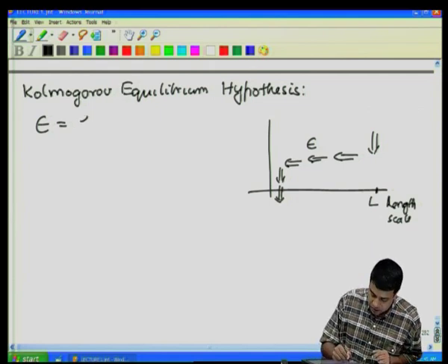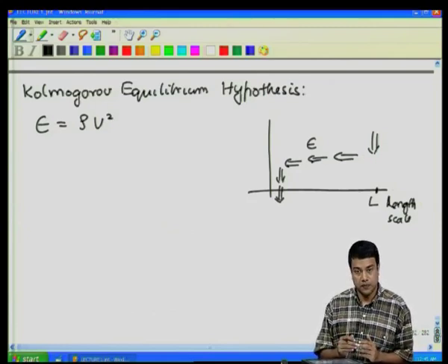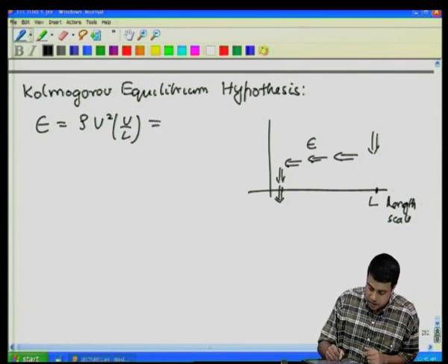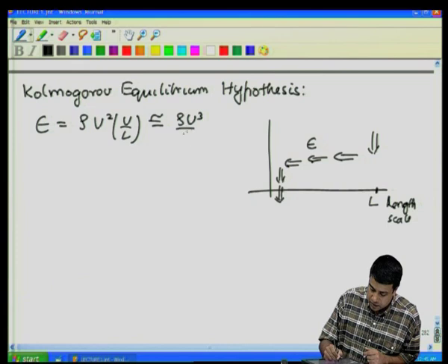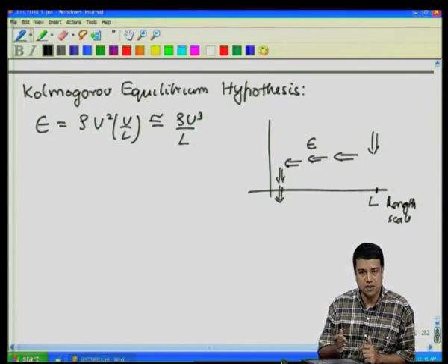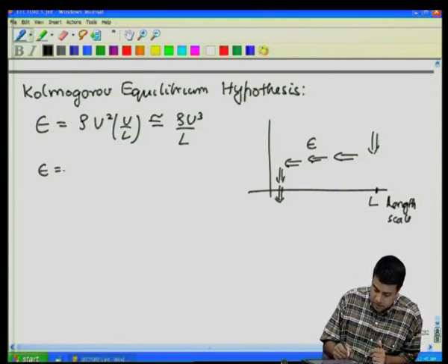So, you write it as the density times u squared, where u is a velocity, per unit time. The only time scale for the large scale flow is U by L, because that is the inverse of the strain rate for the large scale flow. So, you would expect it to have dimensions of rho U cubed by L. However, rather than defining it per unit volume, you could as well define it per unit mass, because the density is the only thing that contains the mass dimension here. So, epsilon is commonly defined as just U cubed by L.